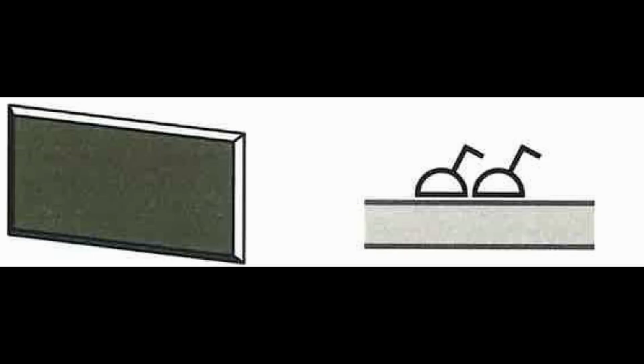2D or 3D, understanding representation. One of the most important concepts in family creation is the distinction between 2D symbolic line work and 3D geometry. In many cases, the 2D representation of an object is completely different from its 3D form. A perfect example is a light switch. In 3D, it's just a small rectangular extrusion, but in 2D, it has a very specific symbolic representation used across the industry. This separation is intentional.